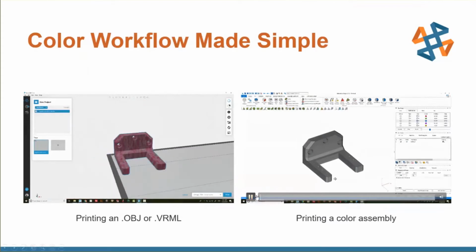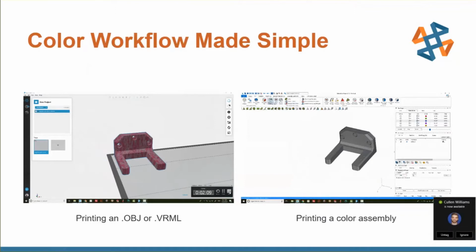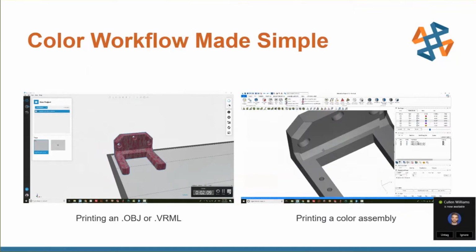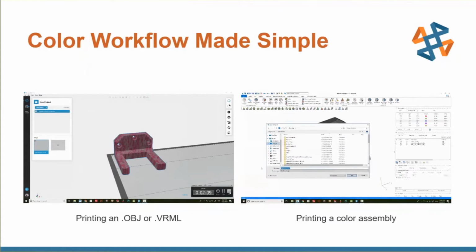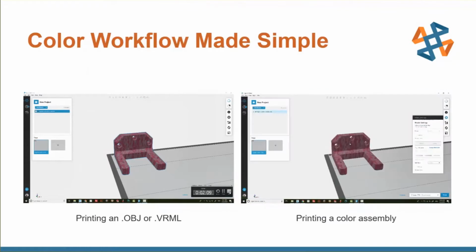So in contrast to that, I'm going to show you bringing in a multiple STL assembly that I'll assign colors to individually in GrabCAD Print. So here there is no color assigned to my model when I save it out, and when I bring it into GrabCAD, I'll import all the files as an assembly.